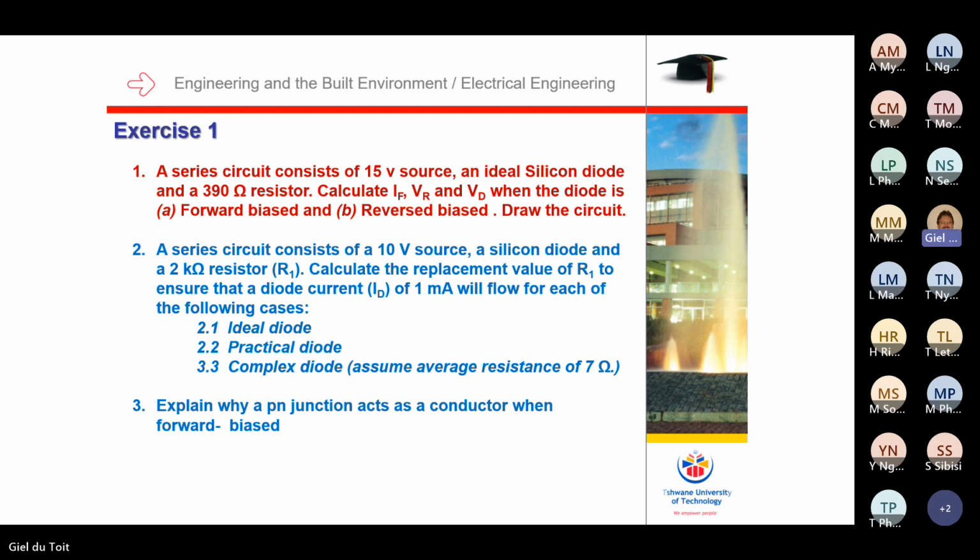So guys, you see, it's a wrong current. But we want 1 milliampere. To get 1 milliampere, I must divide that voltage now rather by that 1 milliampere current, divide by 0.001. So if I do that, I can see my replacement resistor will be what? You can do it yourself. It's 9,300 ohm. So the answer of this is 9K3. So the second one there, it's 9K3. So I'm going to write it 9K3.